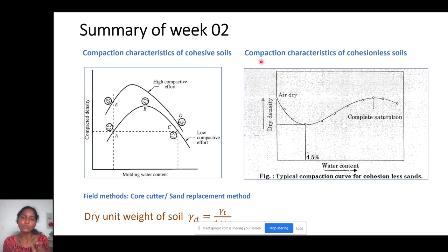This meniscus usually forms only in thin tubes. If you have a bigger pipe of 20 meters or 10 meters, you will not find this meniscus. In the same way, capillary action also will be formed only in thin tubes. So when we have a provision of thinner, connected air voids, that's when this capillary action will start. Water always wants to come up.